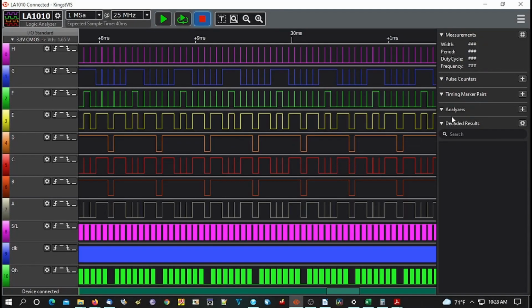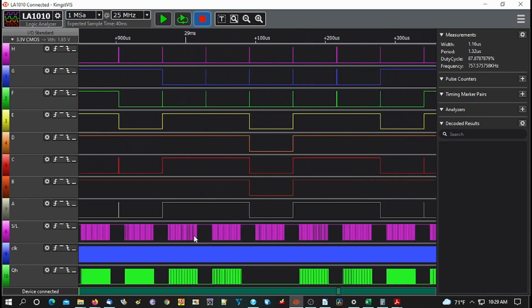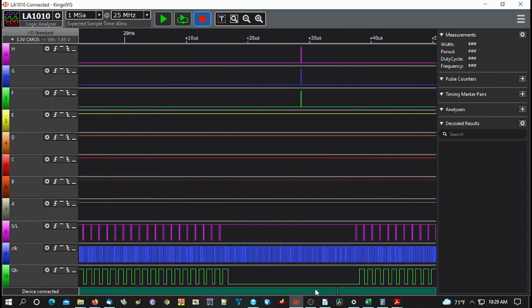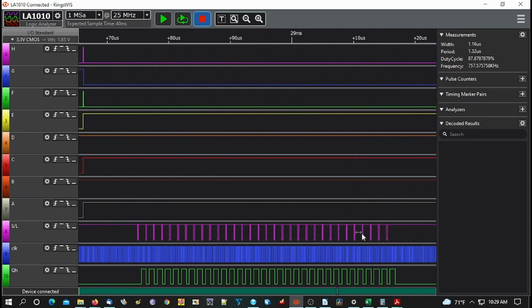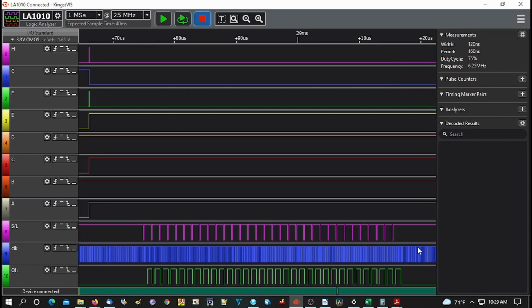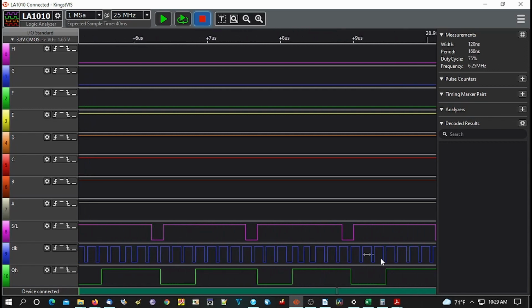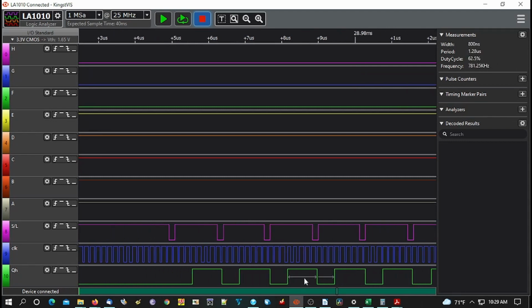The logic analyzer is on the 8-bit shift register. We have the 8-bit inputs A to H, with the load trigger, the pink trace, the 6 MHz clock, and then the final output is green, the QH. Interesting to see each input has a regular blip on there.